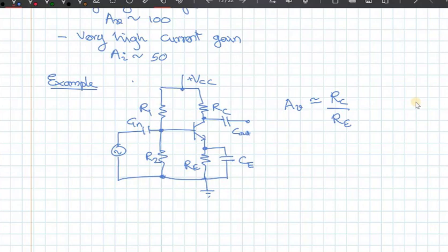Actually, it is not. The reason is that though in the transistor we draw the base-emitter junction like a diode, there's a resistance to it also. It is not an ideal diode. So this resistance, which we call the dynamic emitter resistance, simple RE, is there.